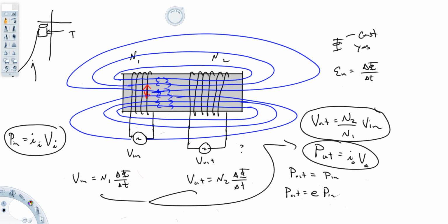The voltage on this side heading to your house is 120 volts RMS. The voltage on the other side of the line is probably around, I'm guessing here, 5,000, give or take, because electrical power is generally transmitted at high voltage to minimize I²R losses. And by the way, it's maybe 5,000 on the other side of that transformer, but if you go quite a ways, like between towns, it's much higher than that, probably 20 or 30,000 volts.